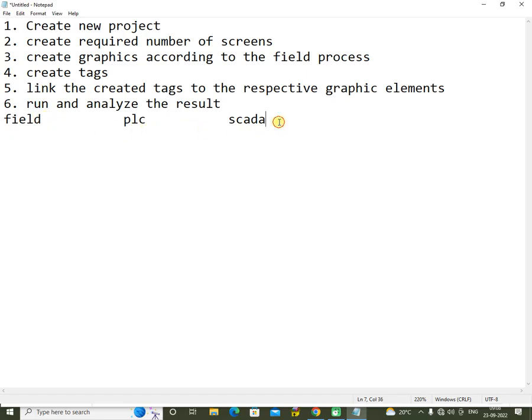In the PLC I will be giving an address. If it is an input in the controller, say a Delta controller, the address is x0. If it is an output, I'll address it as y0. This is the address, and I'll give a comment for it.